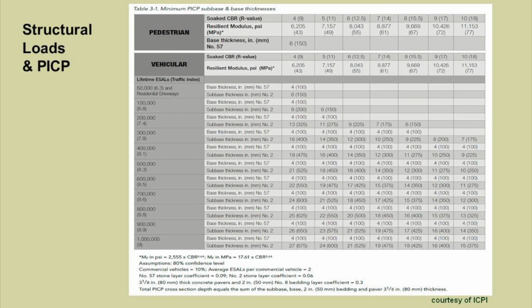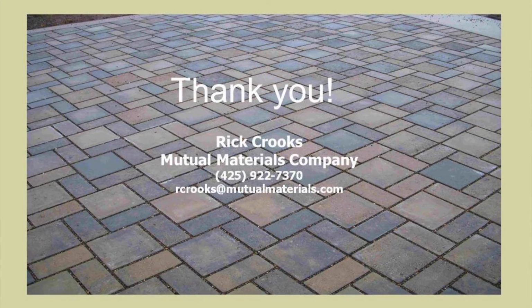Now, I don't expect you to be able to read this, but there is a chart in the ICPI design manual about balancing the structure and hydraulics capacity of these systems. So this is a chart that talks about the structural loads. Basically, it's designed very similar to an asphalt section. Number of ESALs, the more ESALs you have, the thicker the base will be for structural performance as well. Typically, what I've seen in our area, hydrology governs. I'm not sure that's always the case, but usually you design for the hydraulics first. You go back and check it and see if it'll perform structurally. It usually does. But there is a chart there to be able to tell you that.